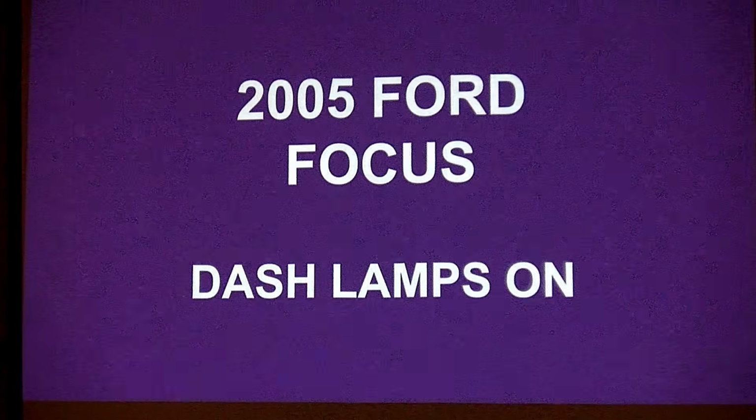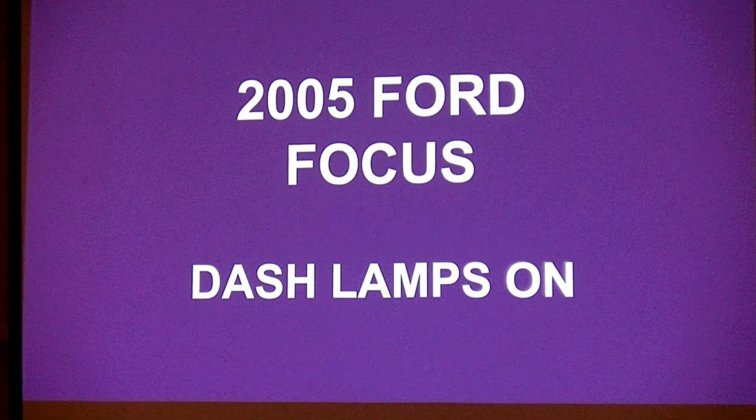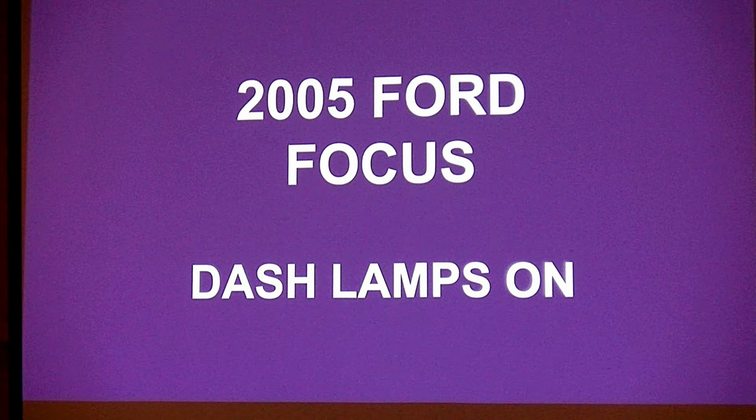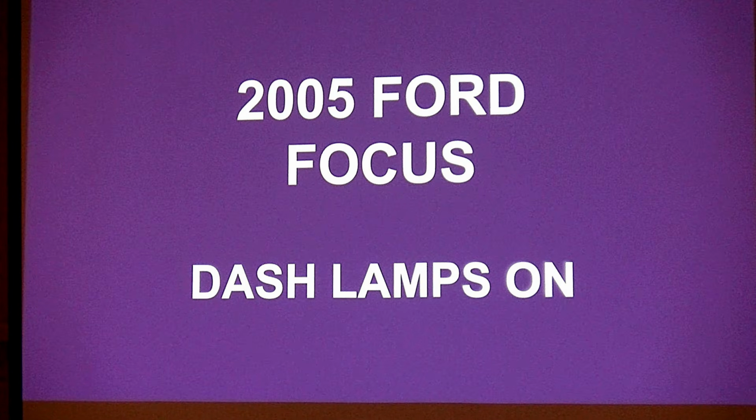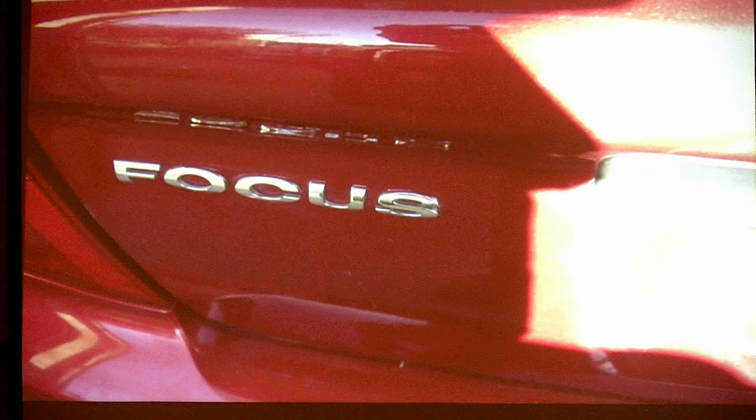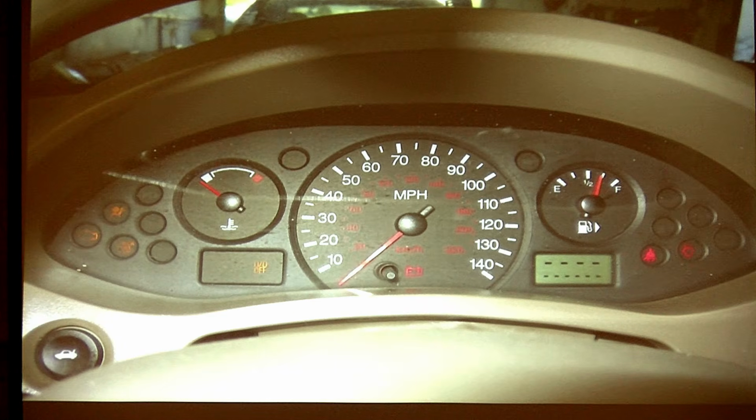It's not that complicated. 2005 Ford Focus, the dash lamps are on. When I say the dash lamps, the driver information panel, everything is lit. Car starts and runs, rest of it's working. Here's the dash system. We can see every light is on the dash, and I have no gauges, but the car's running, but I don't see any tach signals. So basically, well, there's not a tach there, so I misspoke. But basically, nothing's basically working here.